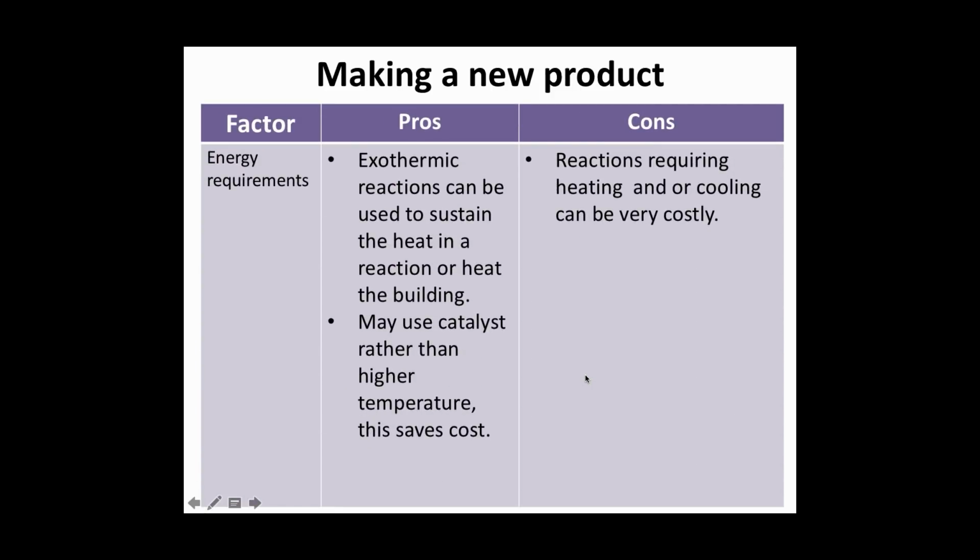Energy requirements. Now, this is probably one of the most important factors, because if you don't consider this at the start of your design, it can very severely affect the way that your reactions will run. Energy requirements refers to literally, does your reaction require energy? The answer is yes, unless we are talking about a spontaneous reaction. Even in the case of a spontaneous reaction, it may release heat, so you do have to deal with this heat. Or some reactions require heating.